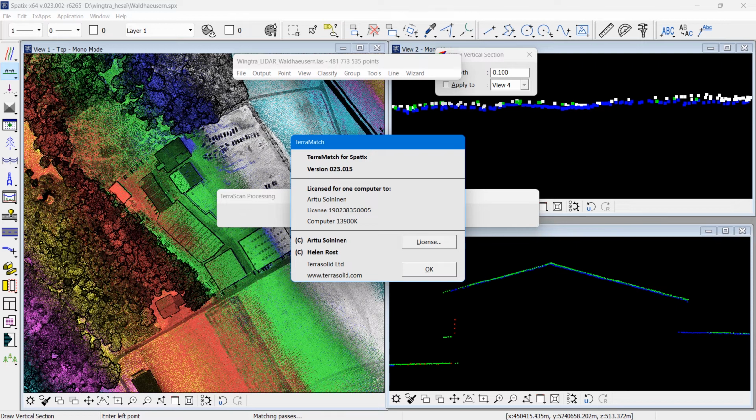And practically always with airborne data, we do want to solve and correct for heading roll pitch per flight session, a systematic bias in our trajectory solution, a small heading correction, small roll correction, small pitch correction to apply to the data. And then depending on the system, I may choose additional levels of corrections to apply.